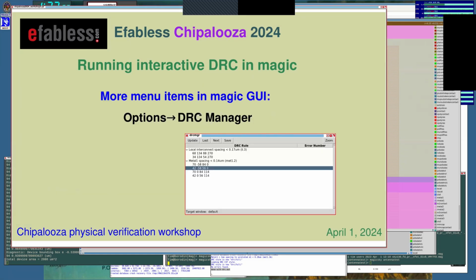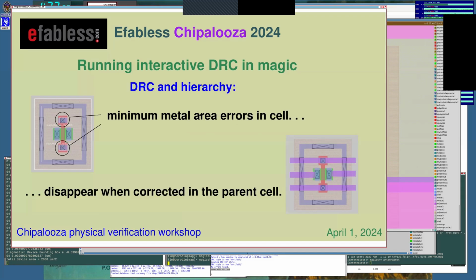Very quick tactical question on placement of an NMOS device inside deep NWell. The question was, do I need to place a P-well in deep NWell before placing an NMOS device?